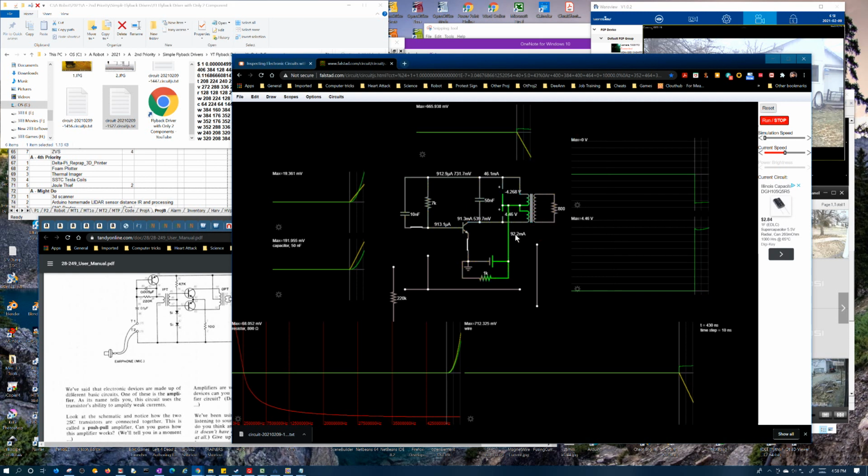See, this got 91 milliamps versus 92 milliamps flowing through it, but remember that current's flowing through this coil, so even though it's got 46 milliamps, it's actually coming from this field charging up that's supplying this current primarily. There's very little difference here. You get 91.3 versus 92.2. That's like a milliamp difference, yet we've got 46 milliamps up here. Where's that coming from? Well, it's coming from this coil right here.